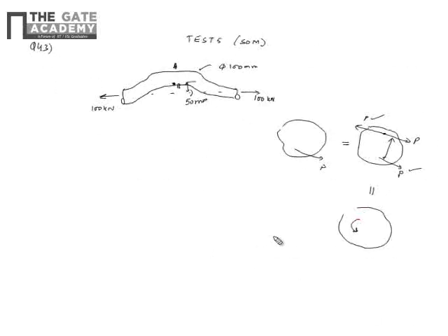That is the couple which I am denoting by M at this point, and you have the force P. So basically any load at a point can be considered as a load at another point with a couple, and if the distance is E, M would be P into E. So any load can be considered at another point as the same load plus the couple.